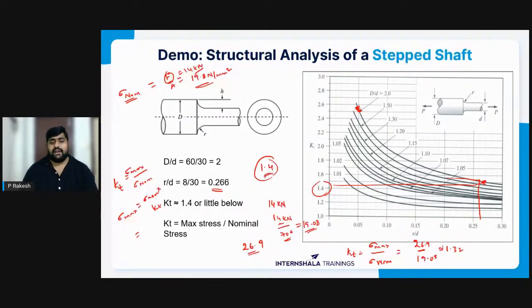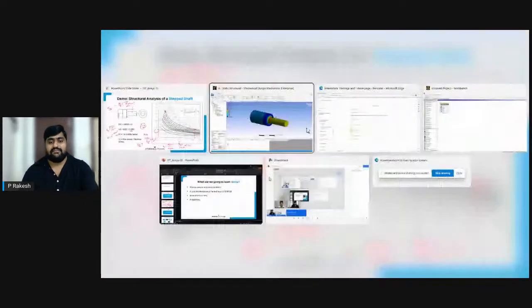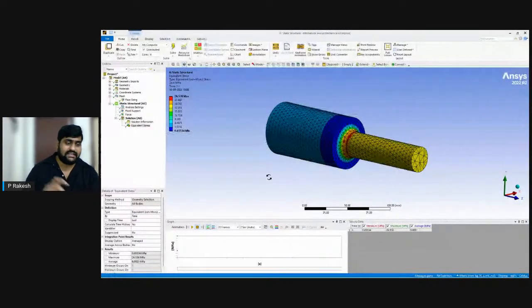If we change to different meshes and different mesh settings, and perform what is known as a mesh convergence study, then we will be able to identify the final solution. So this is basically it. These are the different steps we use to solve any problem inside Ansys Workbench, or let us say any FEA software in general.